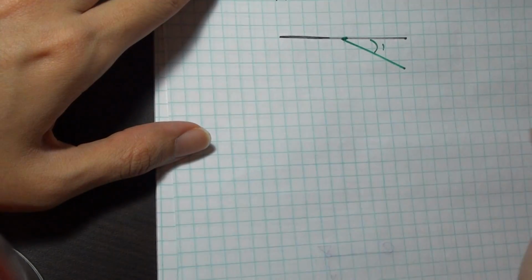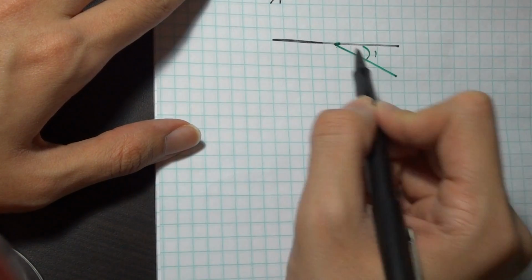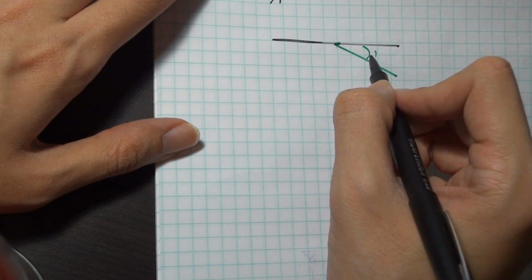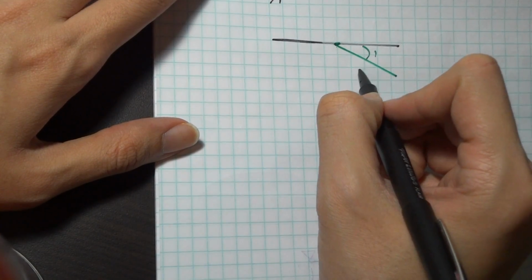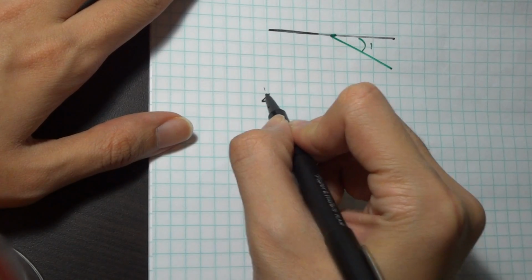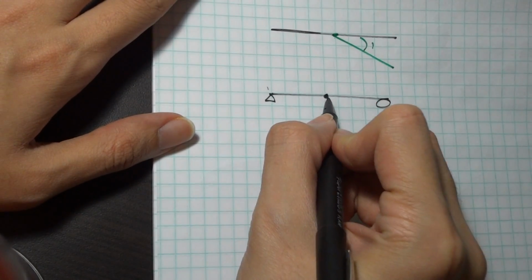Again, I had to maintain the original boundary conditions. This is a rigid element, this is a rigid element. By rigid I mean it can't bend. The angle between these two rigid elements is 1. If I go back to my simply supported beam here, let's say I'm interested in the moment here, I would apply a unit rotation here.